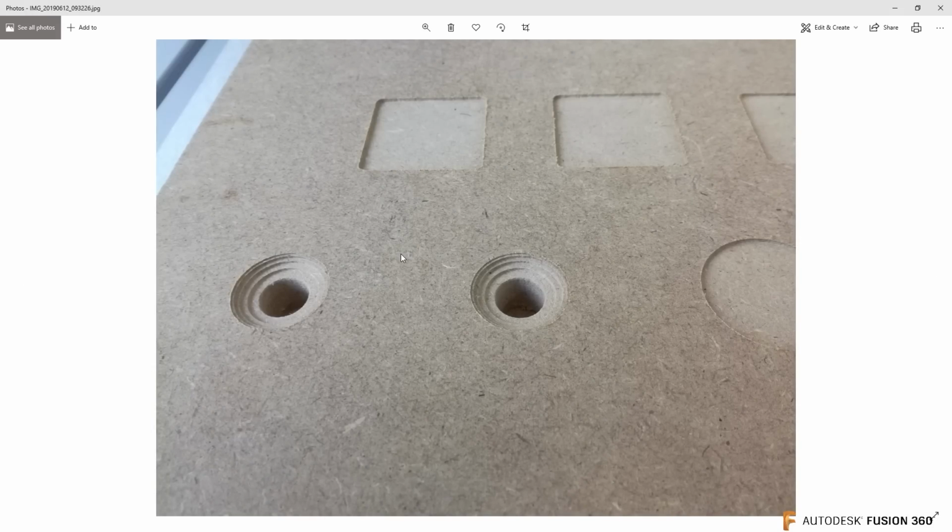So I'm using a 5mm flat end mill, and I don't get any rounding of fillets in the small holes. The holes become too small, and I'm imagining what you're probably doing is a little bit the same as what happened earlier with the tool belt.